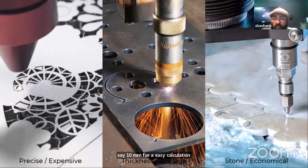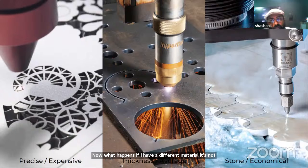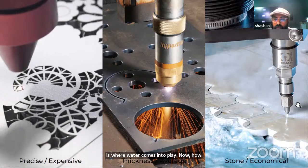Now, what happens if I have a different material? It's not metal, it's stone. What do I do with that then? If I use plasma or laser, it won't really cut stone. And stone is also quite thick. It can be anything between 25 mm to say 100 mm. What do I do with that? That is where water comes into play. How a water jet works is there's a jet of water flowing, and granules of sand are thrown into it.